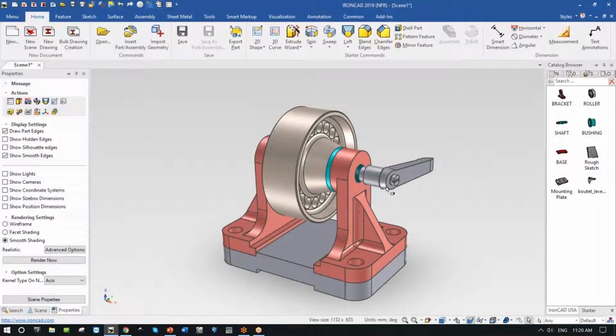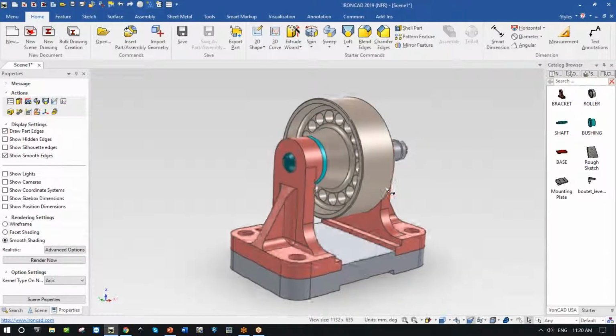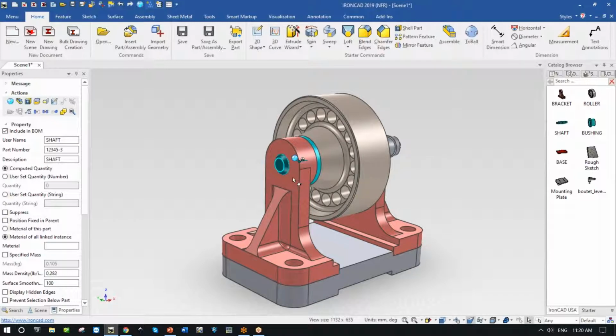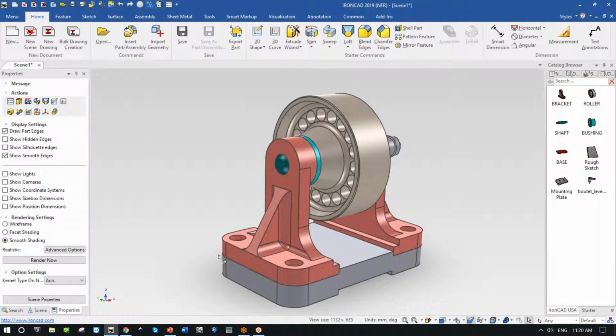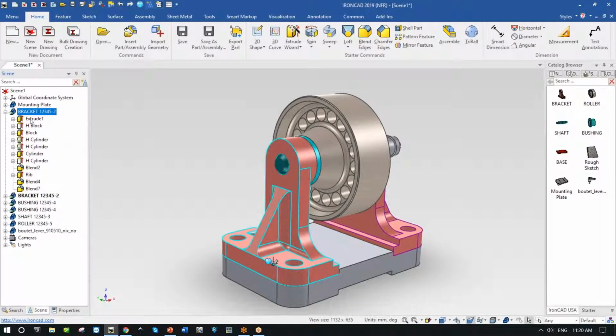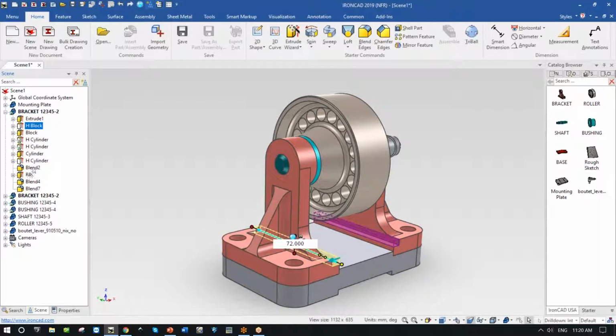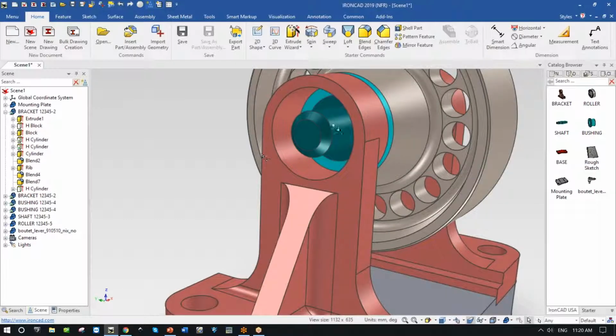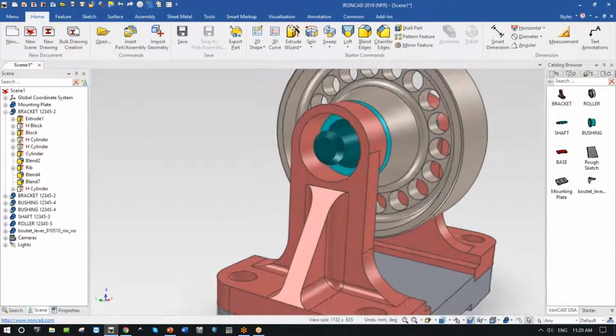Now, I know Joe's going to get upset with me, but I have to look at this. He designed this part, and I didn't actually like the way he designed it because he's got this shaft directly on the metal. As an engineer, I'm looking at that and I'm going, Joe, I'm concerned because of this bracket that you originally designed with all these different pieces. I happen to know down here that you did a hole, and I'm going to make that 24 and open that up. If I look inside here, I can see, oh, he's got metal on metal. Well, I don't want to do that.